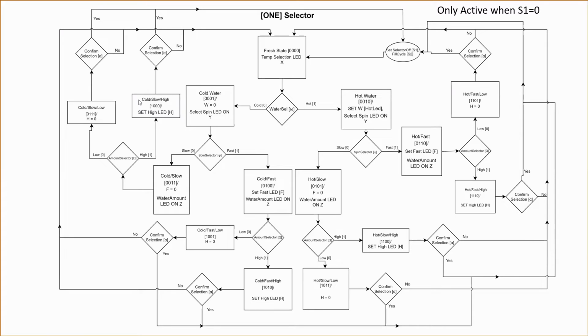But it can easily be modified if, for example, this 5 seconds, as you just explained, is not long enough, you can easily modify that. And I like very much your final choice of PAL. I think you perhaps meant to say, and might have forgotten to say, that the PAL is the only device that has registered output, so you could do without all those flip-flops. That would be yet another advantage, especially in our case, since those would take up quite a lot of space, even the smaller flip-flops. So I really approve and like your final choice.